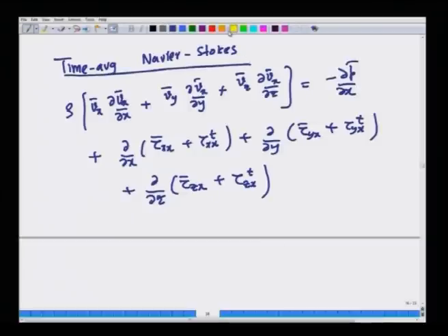It is for the mean or time average quantities with bars, but this is not the same as the time averaging of the Navier-Stokes equation, because once you time average there are these additional contributions which are in general non-zero. So, you cannot simply put bars on the entire Navier-Stokes equation and say it is time average, because of the non-linearities in the convective acceleration term.